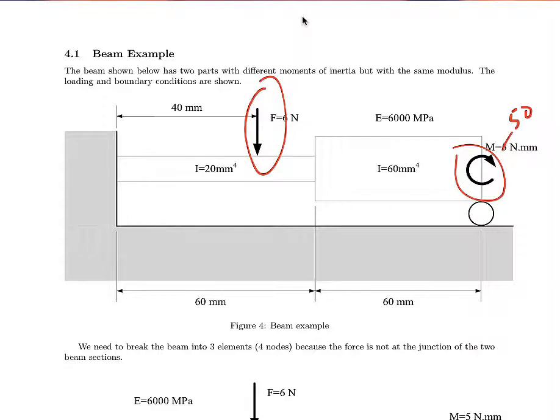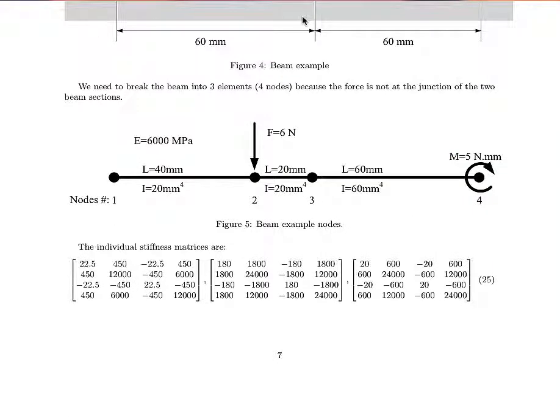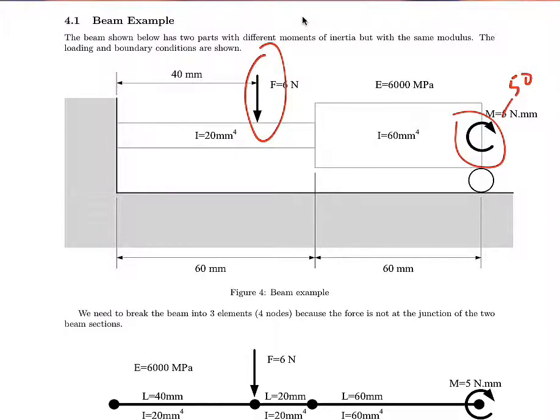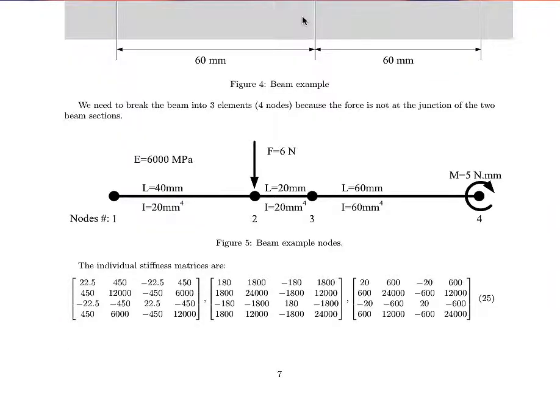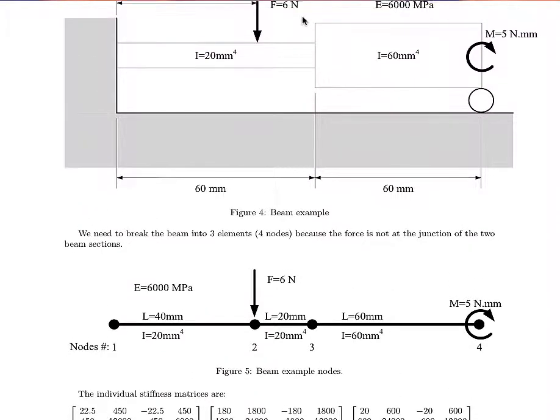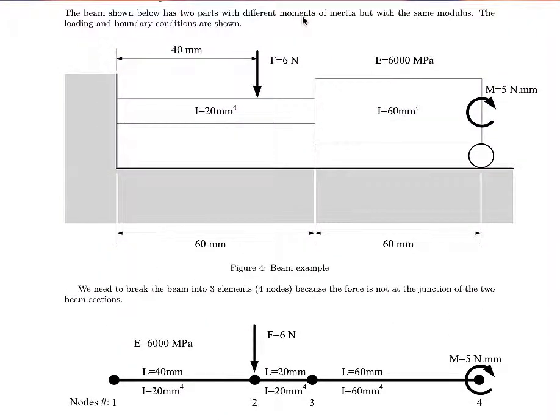on that node. So if I simplify, instead of making the beam look like this, for computational purposes we have 3 beam elements, one connecting node 1 to node 2, then node 2 to node 3, and node 3 to node 4. And we divide it up this way because we wanted to get more detailed information between the applied load and the shoulder of the shaft in this region here.